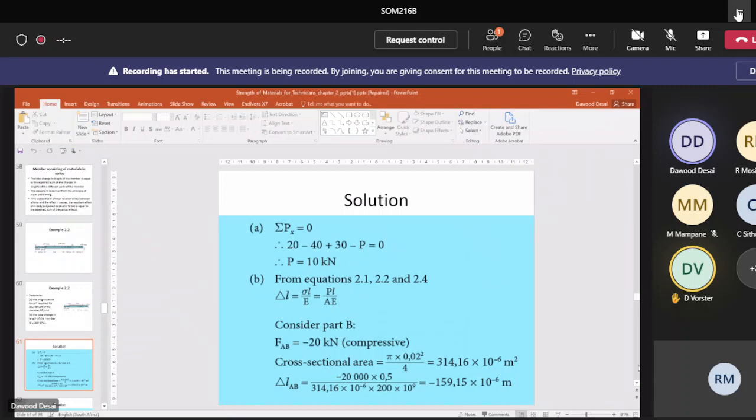Very, very easy. Okay. And you've got some pipe placed inside another pipe. They're giving you the diameters or whatever, and the plates are subjected to a compressive load of 75. So it's like the series setup where you had end loads. Now you've got one pipe pushed into another pipe. A lot of examples in practice of this, eh? The outside loading is 75, and they want to know the stress in both materials.